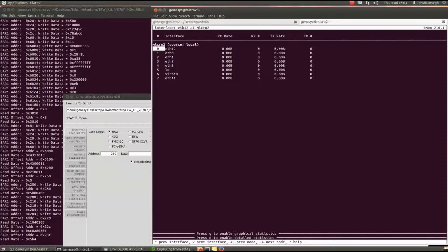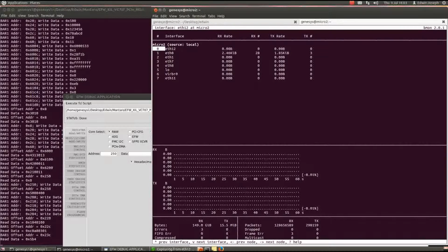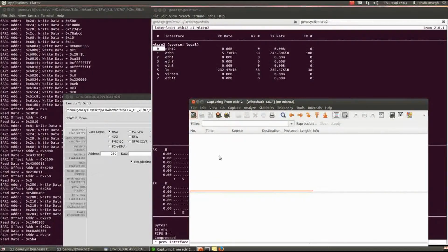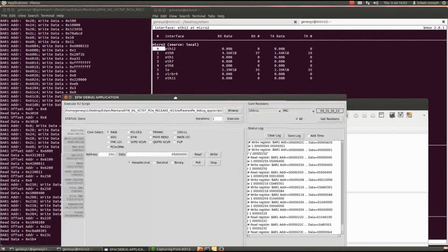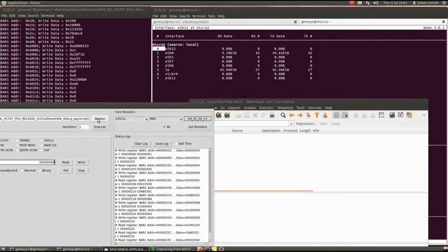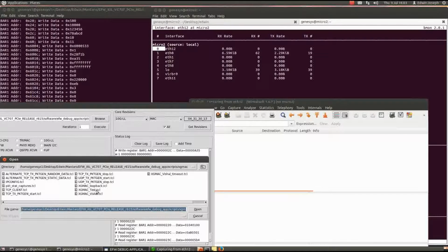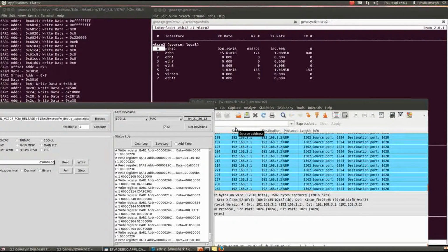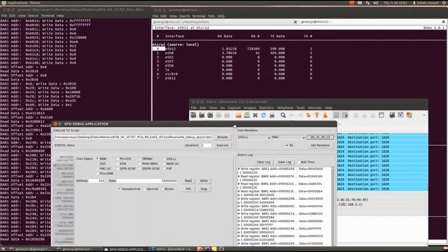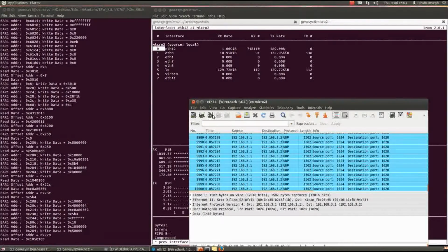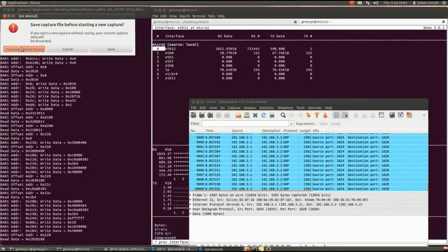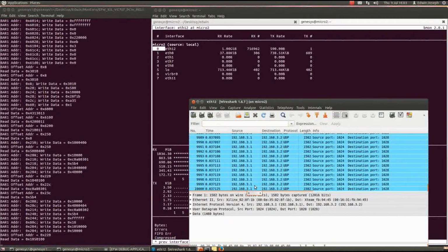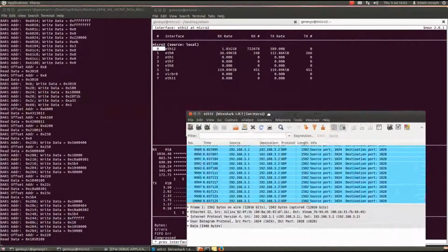The client system is set up to receive the UDP packets from TOE, and we initiate the traffic generation of UDP packets at 10 Gbps using a TCL script which configures the traffic generation enable parameter onto the FPGA. The speed of the client where it is receiving is 1034.37 MBps, which converts to 8.7 Gbps. The packets are captured 10,000 at a time or any other small number so as to avoid Wireshark hang.